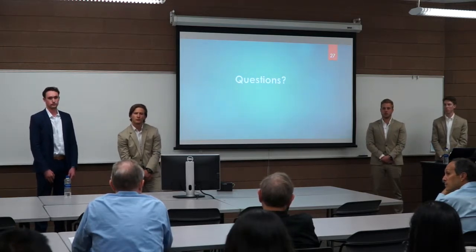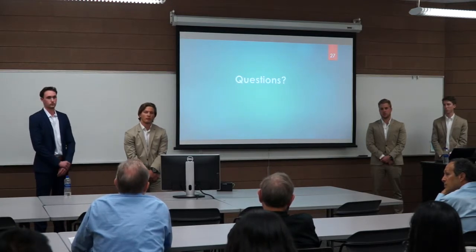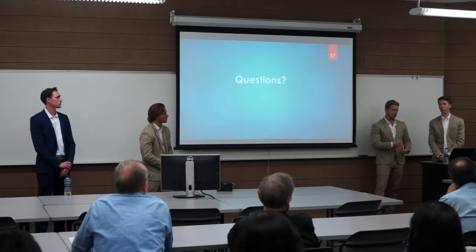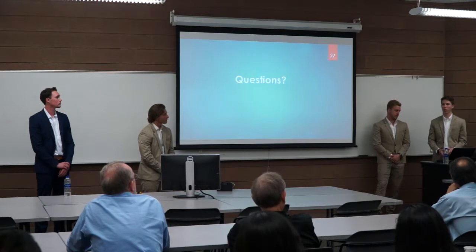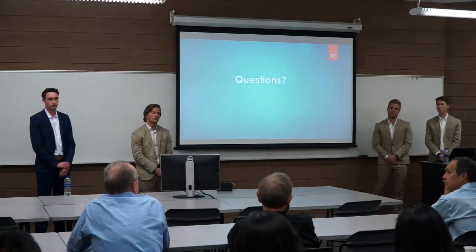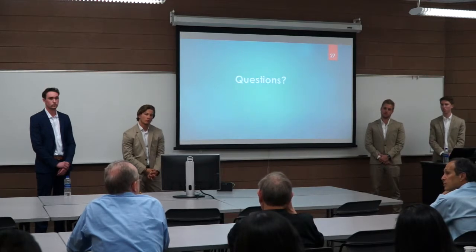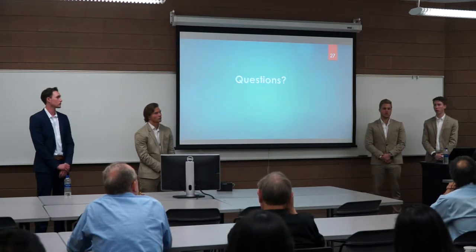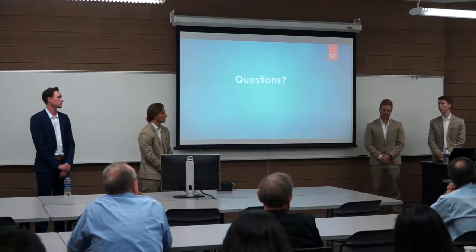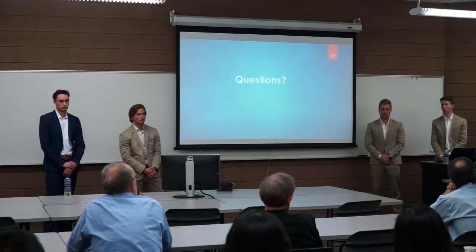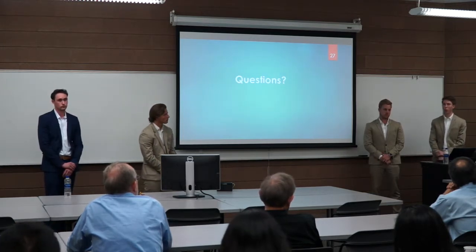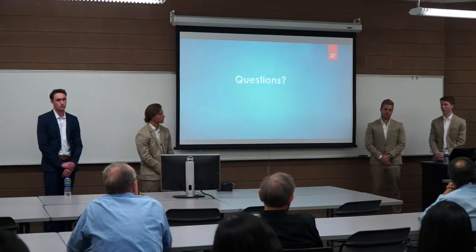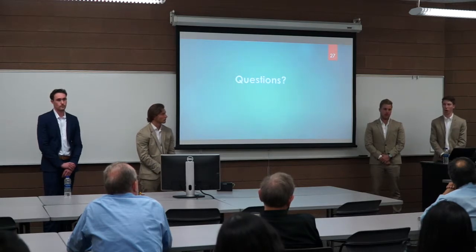And you said you fed it through a low pass filter? You're talking about the .wave files? Yes. We ran a Python library on those files as they came in to get our kick drum out. But again, you just used the library. Do you think you're writing your own filter? We did, but it would have taken too much time, and with the integration that we already had with our wave files, it made our software integration much more streamlined. That's why we chose Python at the beginning of this project. If we had more time, we would have run it all in C or C++ to make it a lot faster, but to code the algorithm quickly, we ran it in Python.